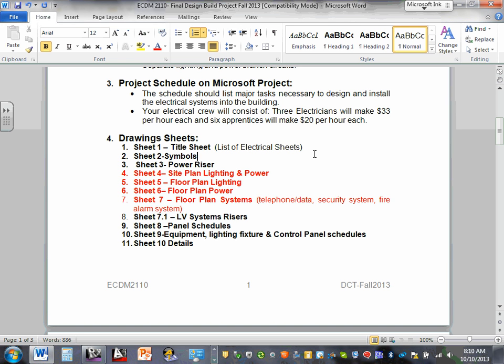Like I said, guys, yesterday, there are views and sections that you can drop. You can drop a view in a sheet, you can drop a section, and you can drop a drafting view. A view, a section, and a drafting view. For anything component-wise, like switches, receptacles, lights, low voltage, these are called views, sections in the building. For anything that you need to draft, we call it a drafting view.